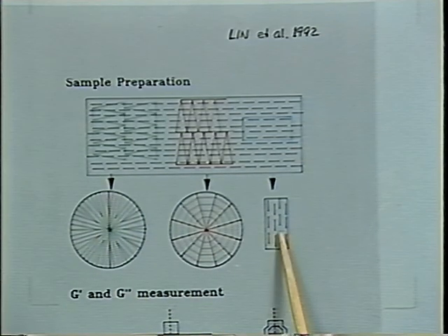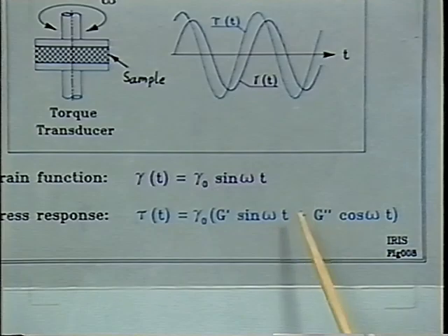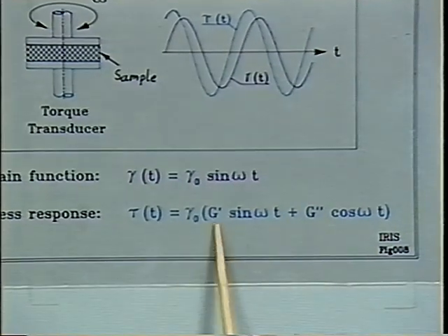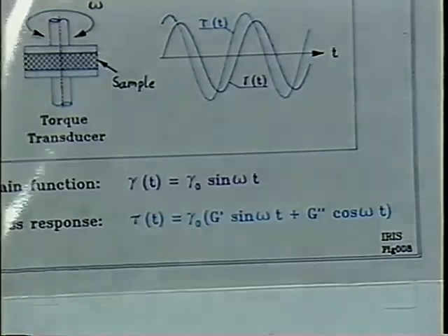We couldn't do it in the third direction, so we are just probing the sample by clamping it. So that's a little harder to interpret. But those two geometries we can clearly probe and get very, very nice data. The probing, again, is, as in many cases before, the dynamic mechanical experiment, we get G prime, G double prime. However, there is a directional dependence for G prime, G double prime.